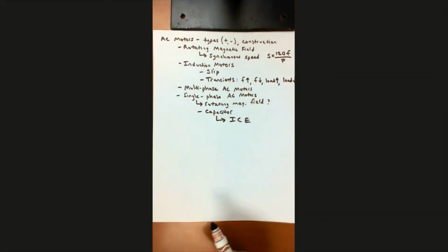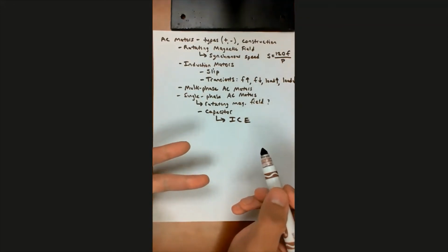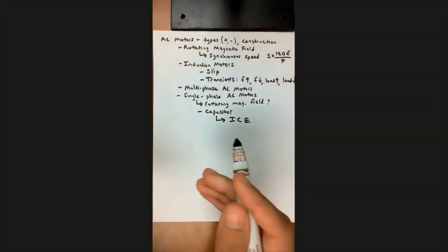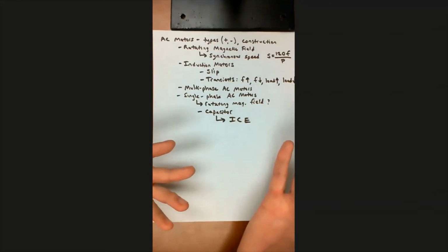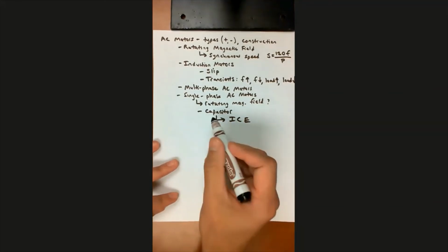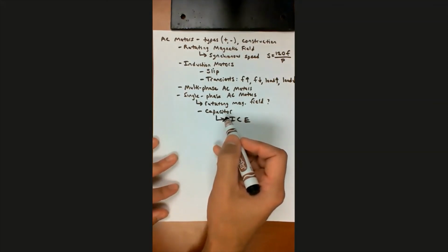And so because the current is out of phase, that's going to do kind of the same thing as we showed back when we were talking about a two-phase AC motor. Remember, I showed you a video about that, the rotating magnetic field with two phases. And then I said, well, actually, in real life, usually they're three-phase. But the two-phase actually applies very nicely to the single-phase AC motor where you have one set of windings with the capacitor. So that acts very much like a two-phase AC motor would. All right, that's most of the things on AC motors that I can think of.